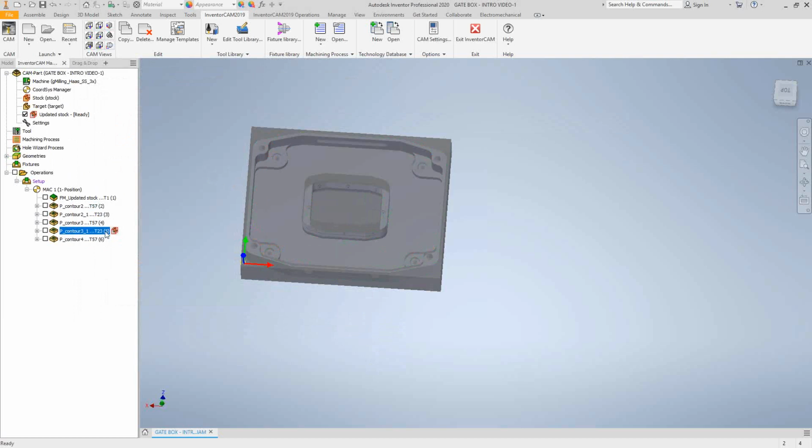By doing a save and copy, they're actually out of order here. You can see that I'm going back and forth between tool 57 and tool 23. What I could do is I can just left click on the icon and drag it to the end. And I'll do the same with this one here.